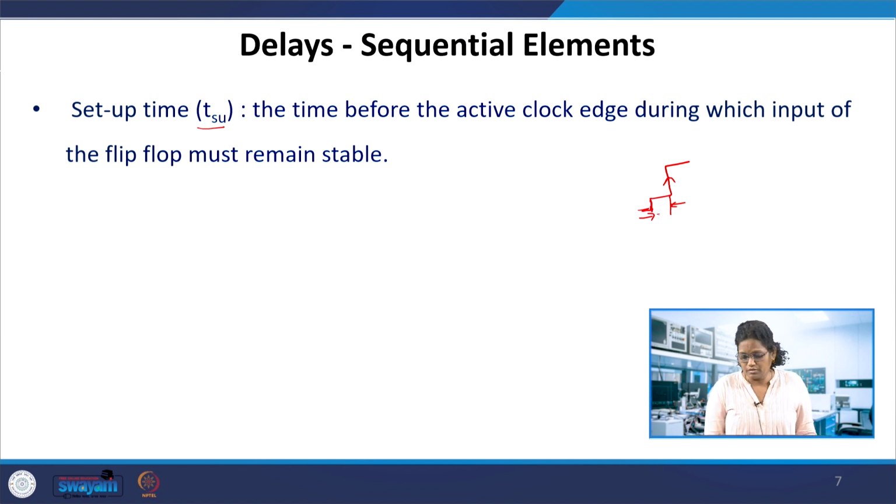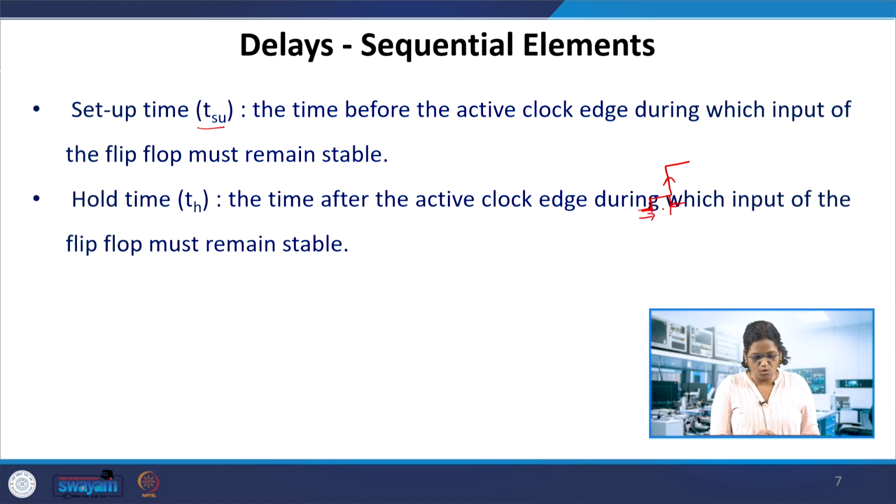The data must not change, and should be stable in that duration. So that is the setup time. And similarly, hold time is, after the flip flop clock edge has arrived, how much time the data should remain stable again. Okay, so this is setup time and this is hold time.